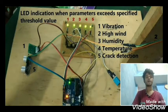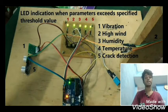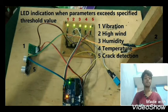Initially, we monitored the parameters through LCD indication. Whenever a parameter exceeds the threshold value, the LEDs blink. In order to know the values of the respective parameters, the LCD is connected and it indicates whether there is a rise in value or a reduction of value. The data are further stored in the cloud through Node MCU. Whenever there is a rise in a parameter, a message alert is given to the registered mobile number.